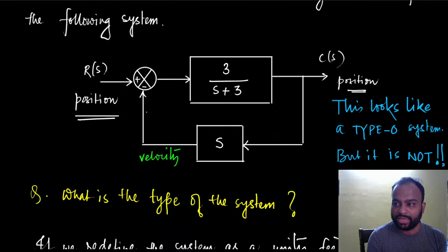So it's a velocity feedback, often also known as a tachometer feedback for your position control systems using motors and everything, right? When you feed back using a tachometer, a device that measures velocity, then you essentially have a velocity feedback. And with a tachometer feedback properly, you can do a proper position servo mechanism. Essentially you can follow position commands properly. Just to understand the discussion here.